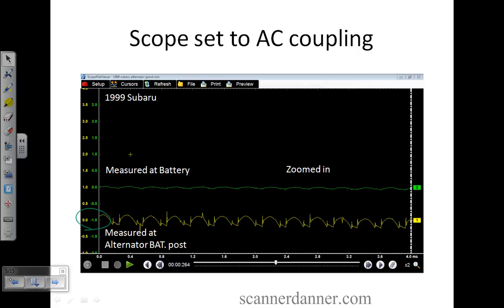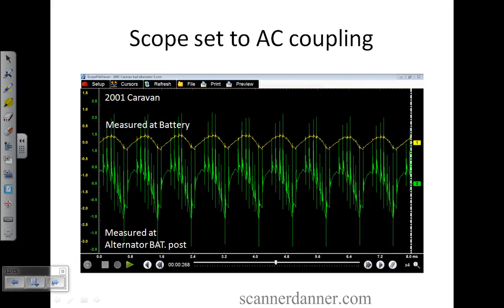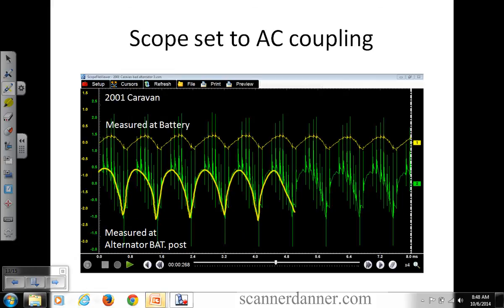And again, all right, so let's go back and look at our alternator with a bad diode. See the difference? Huge oscillating spikes in that. In fact, this one was so bad we could see it at the battery though. If we measured this at the battery with our voltmeter, here's minus 500 millivolts, here's positive. You see, we might be around 300 millivolt average maybe. If we measured at the battery, did we potentially miss it? If we went to the battery, the answer is yes.